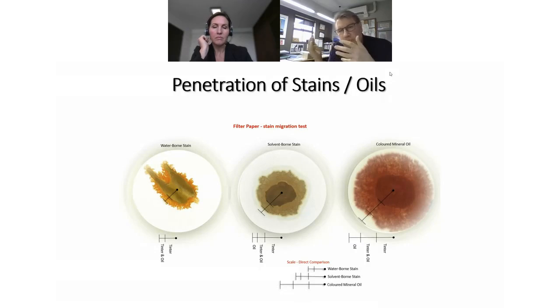So of them, when we want stains, your wood stains for outside, we want the smallest molecule possible, the longest drying time, I'm just saying, and we get the better penetration, which helps stabilize the cell. Now, the cells in timber will still take up moisture, but it just takes them longer to take up moisture if we get a little bit of those sorts of oils in there.